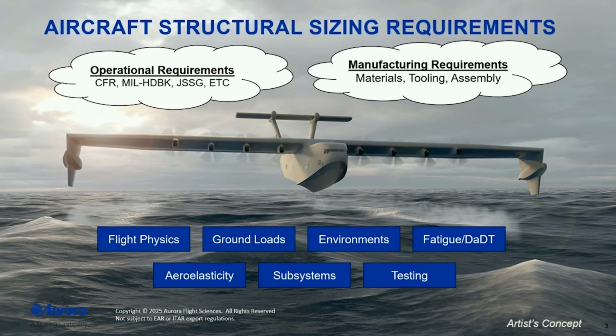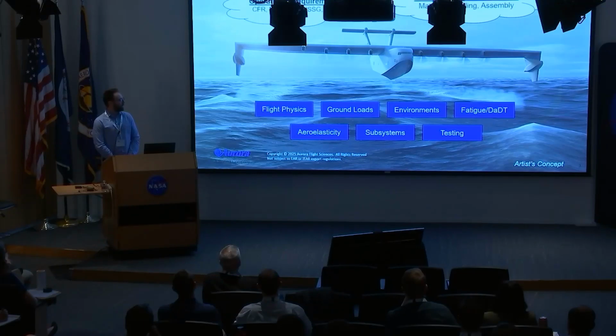That will ultimately lead to sizing and analysis considerations that you have to take into effect as you're performing the analysis. So whether it's the high-level operational and manufacturing requirements, you're crossed with really working with other teams in the product development side to flow in information from flight physics, your ground load considerations, environmental factors and operations, fatigue cycling, as we've heard from other talks, aeroelastic stiffness requirements, penetrations that come down the line when you don't want them, and obviously, ultimately, the testing requirements that you need to facilitate for static proof loading, fatigue loading, or even vibration testing.